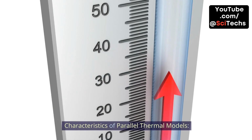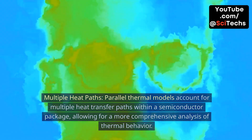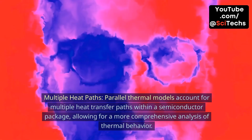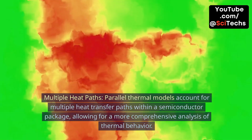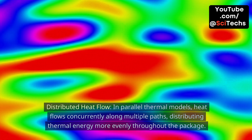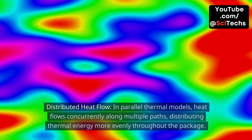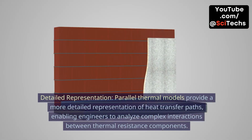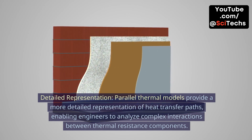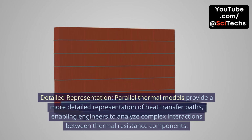Characteristics of parallel thermal models. Multiple heat paths. Parallel thermal models account for multiple heat transfer paths within a semiconductor package, allowing for a more comprehensive analysis of thermal behavior. Distributed heat flow. In parallel thermal models, heat flows concurrently along multiple paths, distributing thermal energy more evenly throughout the package. Detailed representation. Parallel thermal models provide a more detailed representation of heat transfer paths, enabling engineers to analyze complex interactions between thermal resistance components.